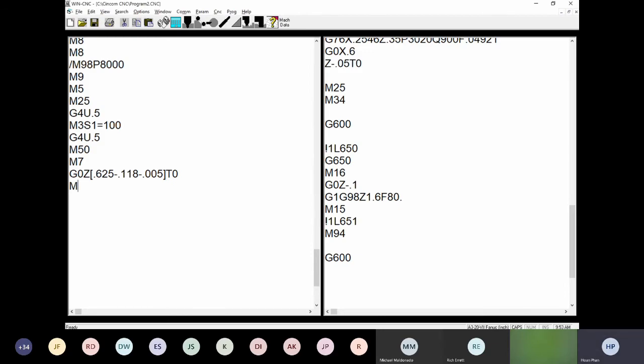And then put the M56 to counterparts. And then that should be it. We're gonna finish it with M2, M99. But then like I said before, we're gonna need to put on the last part program function. So we're gonna go G999 and then N999 right here.